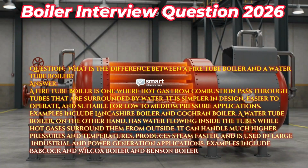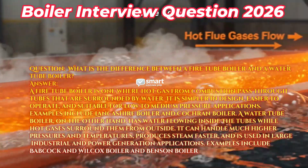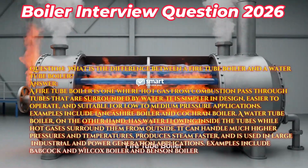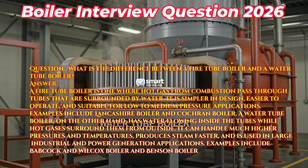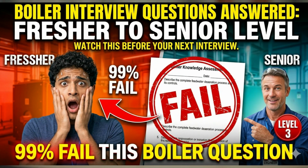tubes. Question: what is the difference between a fire tube boiler and a water tube boiler? Answer: a fire tube boiler is one where hot gas from combustion passes through tubes that are surrounded by water. It is simpler in design, easier to operate, and suitable for low to medium pressure applications. Examples include Lancashire boiler and Cochrane boiler.